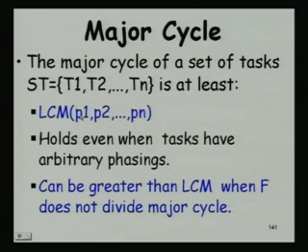So, maybe I can give you that as an exercise: what if the frames do not integrally divide? What will be the length of the schedule that needs to be stored? As a bonus problem, right. It is not there in any book or anywhere reported. So, please try out, what if the frame size does not squarely divide the major cycle, what is the duration of the schedule that needs to be stored.